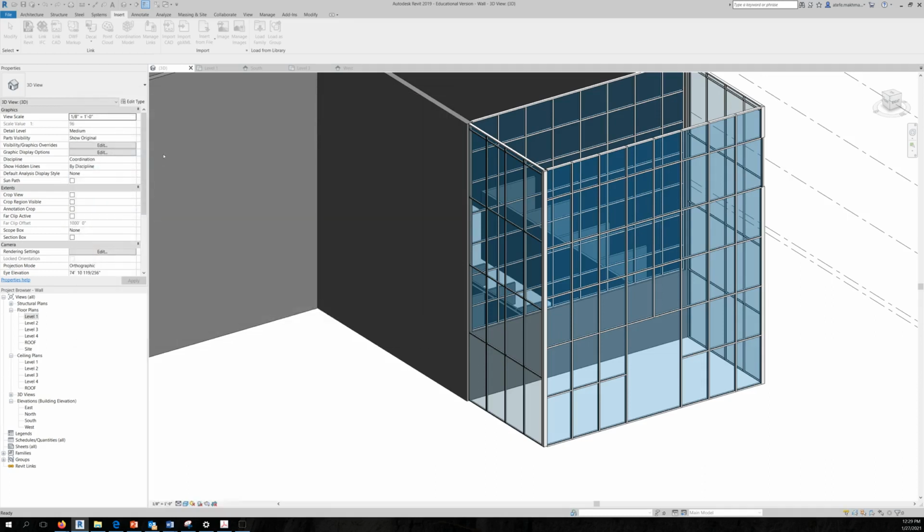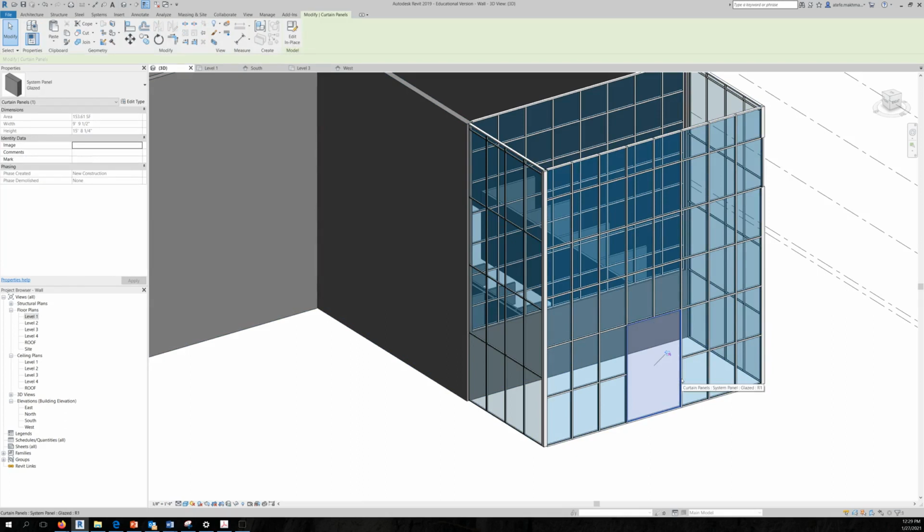So let's use one. Now it should have been loaded. So let's select this opening. To do that, you need to hold your mouse over one piece of mullion, and then you can use the Tab key until it selects that opening for you. If it doesn't, then hold your mouse over another piece of the mullion. It should go through all elements connected, and it should open.